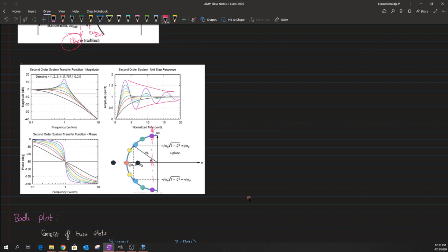So it takes a longer time for us to bring this oscillation down when compared to the other types of pole locations, whereas in this case we have a real part which is quite larger than the previous real part, due to which this particular signal would die out much faster than the previous signal. And as we move further and further, when we have this orange one, let me use a different color, I guess.